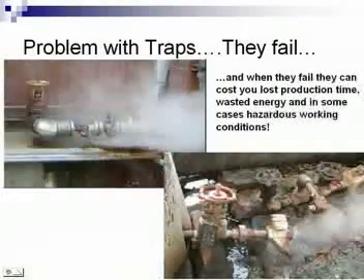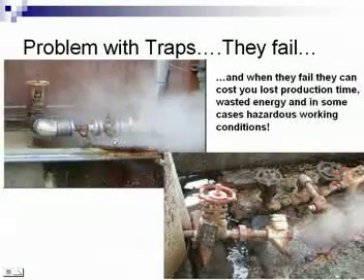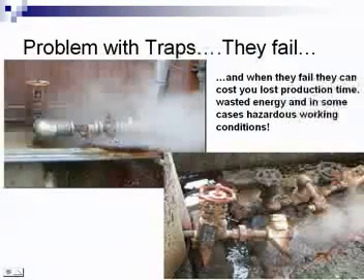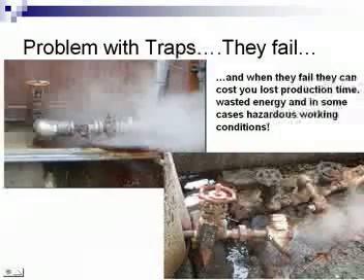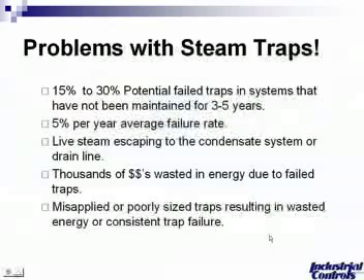This is a very good picture. This is a typical steam system that's been neglected. If you were to look in the upper left-hand corner, we're just depicting a steam trap system, a trap station that is having leak-by, corrosion, and many other problems, obviously. On the right-hand side, we're showing a disconnected steam trap that's obviously in a fail-open position. And if you were to look very closely, it's obviously been tested. There's a tag hanging off of the valve. So just testing the valve or testing the trap is not the only thing you should do. You need to replace and repair that to reap the benefits.